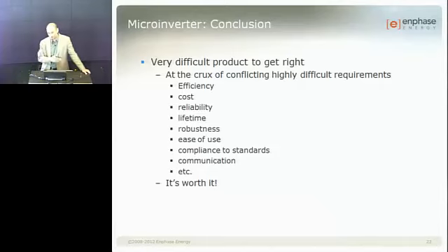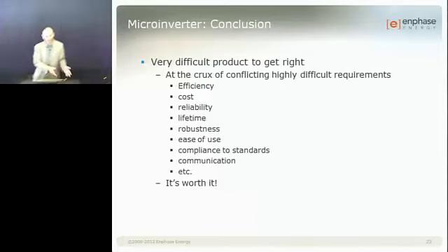and that's one test for 2,000 hours, I believe, and then for another one we go up and down in temperature very fast, and we try to accelerate our failures that way. We find a lot of stuff this way. It's a very difficult science, because in order to do that properly, you really need to understand what the failure modes are. Before you have a failure, you need to know what the failure mode is so you can design the test properly, so there's a little bit of a chicken and egg problem. But by doing this, you can get really close, and we've got pretty good correlation between the failures we get in that test versus failures in the field.